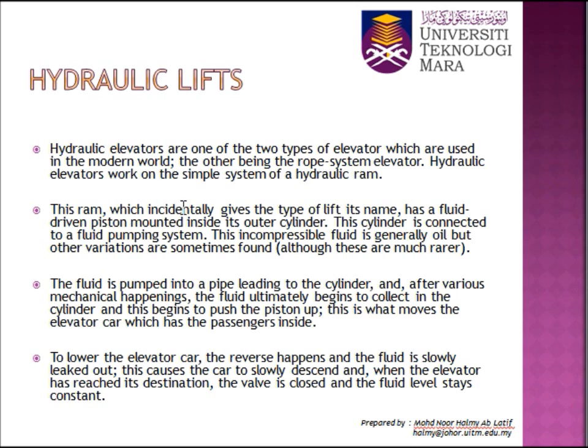Okay, this ram, which incidentally give the types of lift its name, has a fluid-driven piston mounted inside its outer cylinder. Okay, so this cylinder is connected to a fluid pumping system. This incompressible fluid is generally oil, but other variations are sometimes found, although these are much rarer. The fluid is pumped into a pipe leading to the cylinders, and after various mechanical happenings, the fluid ultimately begins to collect in the cylinder, and this begins to push the piston up.